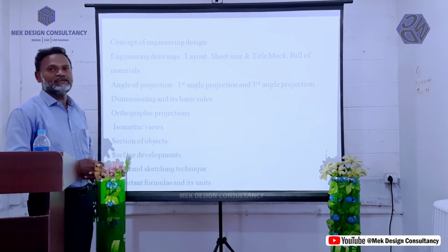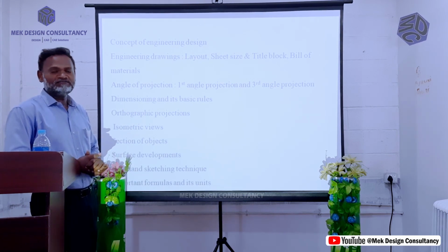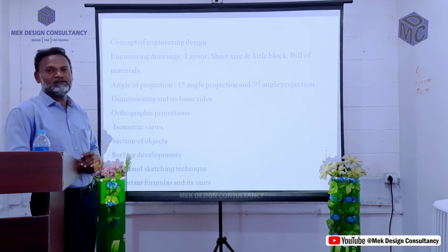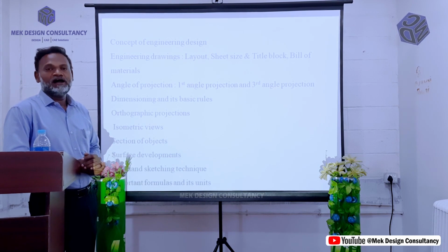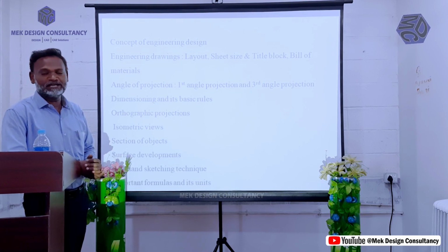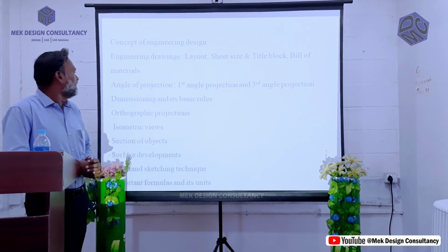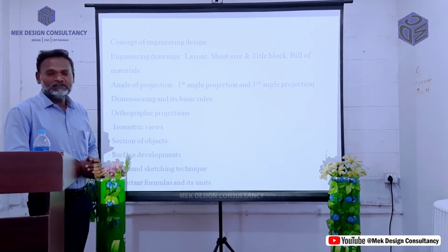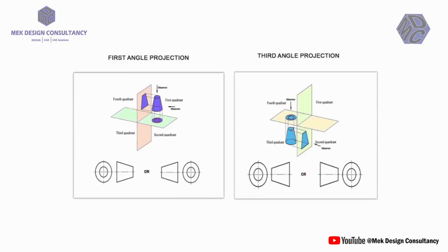In any engineering industry we should know the concept of engineering design, get an idea about the product concept, and make the drawings. For those drawings, the detailing of the title block, bill of material, layout and other parameters is very important. When doing the drawing at a global level, there are two types of projection used: first angle projection and third angle projection.